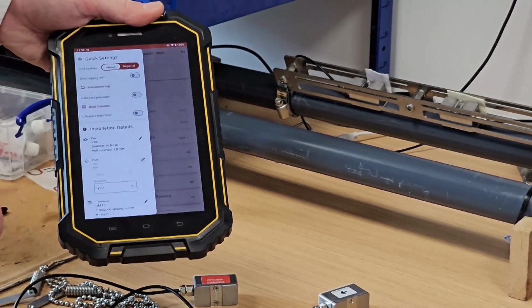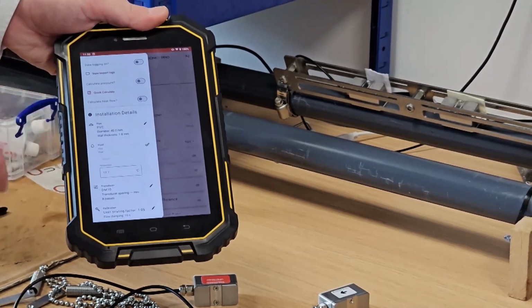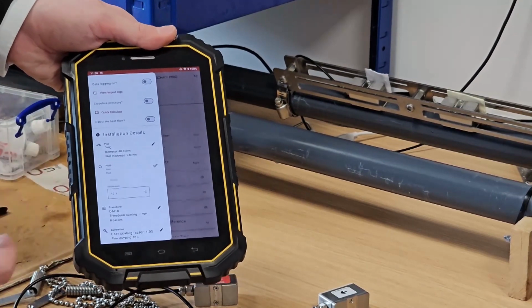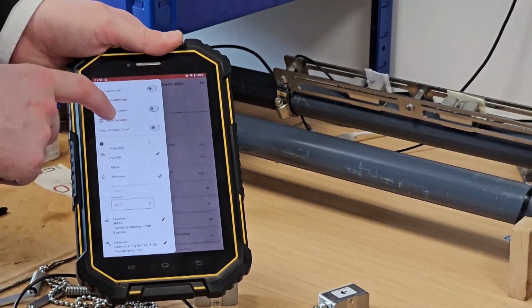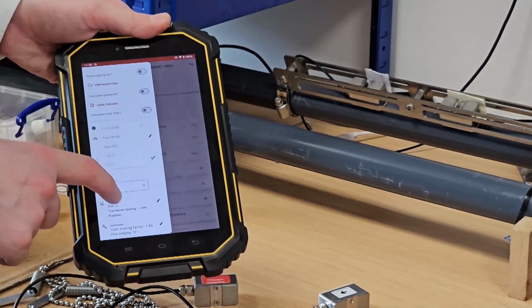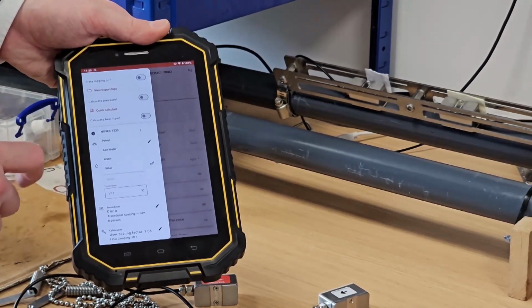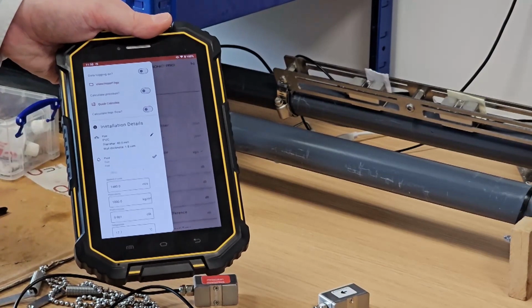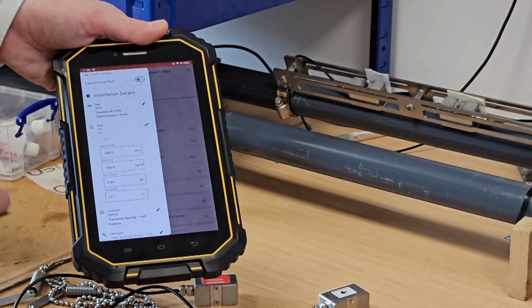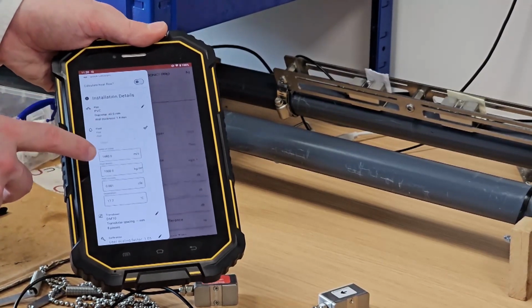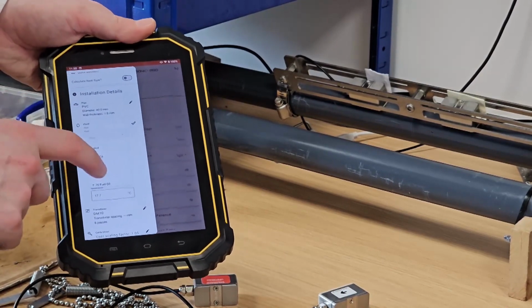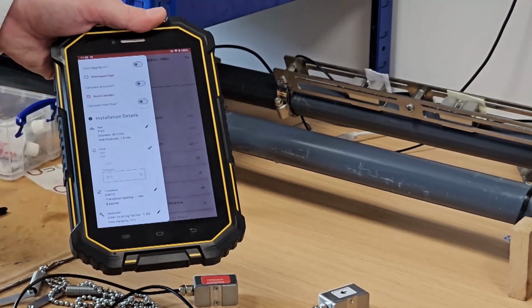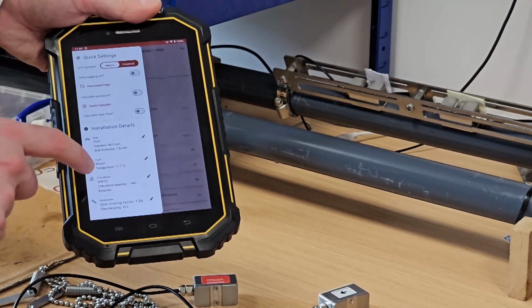Again, in our case we are just testing on PVC, so I can go ahead and select that. Then within fluid, we have a drop down to select the type of fluid you're testing and just the temperature of that fluid. Once again, we've expanded the database of fluids considerably, so there are far more to choose from than in the original version of this device. And we also have an other option here for any not in our database, where you'll be asked to provide the speed of sound, the density and the viscosity of that fluid as well. Once again, this pipe does just have water flowing through it, so I'll leave that as water.